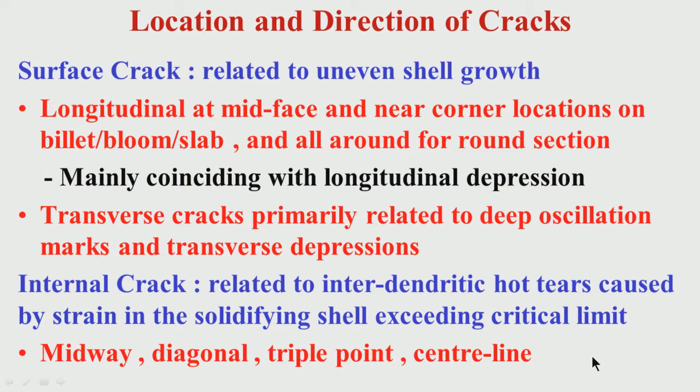If you have an equiaxed zone at the center, you have less central crack and central segregation, because it is getting relatively distributed. But if you have columnar zone extending to the center of the cast, why will the columnar zone extend?